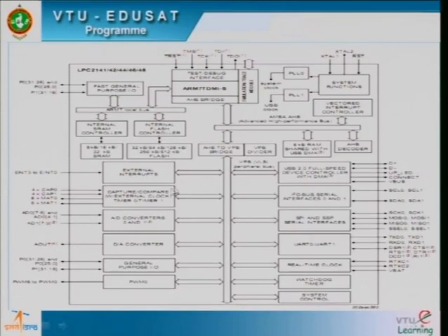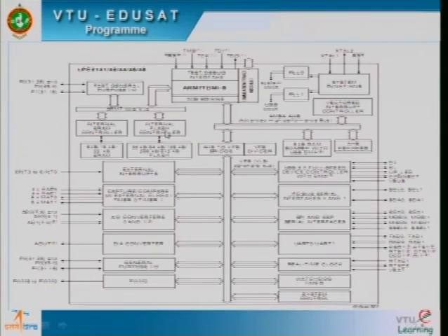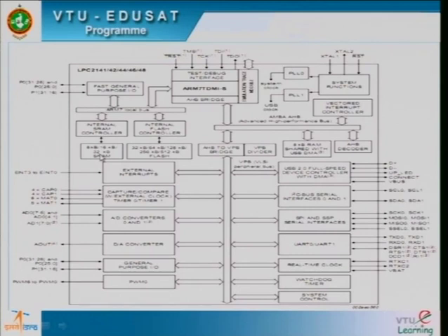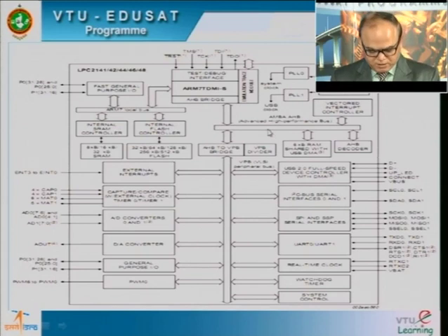On the other side I have the ARM local bus connecting to the internal SRAM and the flash memory controller and so on. The SRAM can have a word size of 8-bit, 16-bit or 32-bit configurations, or 8 KB, 16 KB or 32 KB configurations supported by the SRAM. So these are the various components we have, and this is how the various components are found inside the processor core.